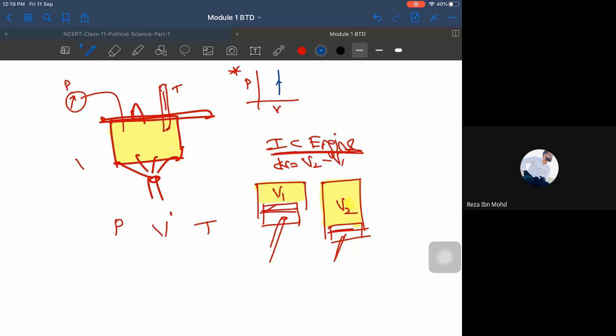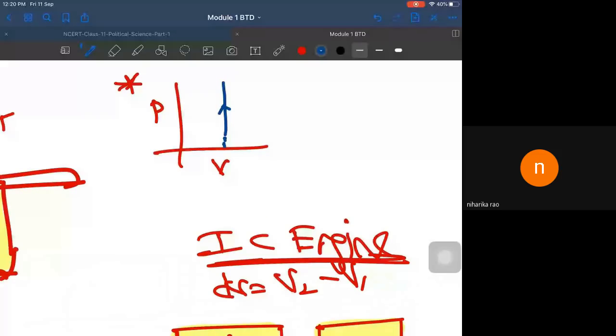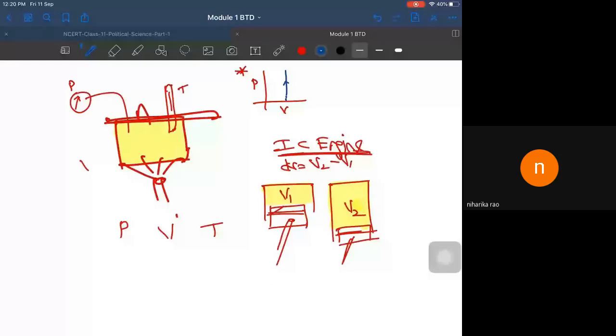Can you analyze things using the PV diagram? The volume is unaffected, is it? Whenever there is a change of time, the same volume is there, which is the volume of your pressure cooker, okay? But what happens to its pressure? The pressure is raised from here to here when you are supplying the heat. This PV diagram exactly represents the process, yes or no? Yes, sir. So this is how you will analyze the thermodynamic process.